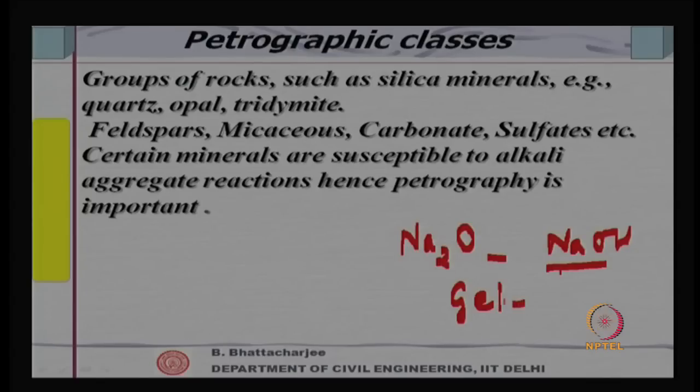This gel adsorbs water and increases in volume. And this expansion in hardened concrete can cause cracking. We will look into this issue of alkali aggregate reaction in detail when we talk of durability of concrete. So, certain aggregates are prone to such durability problems and cause deterioration of concrete structure.